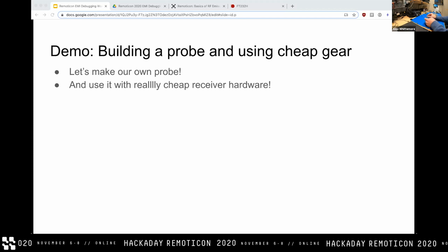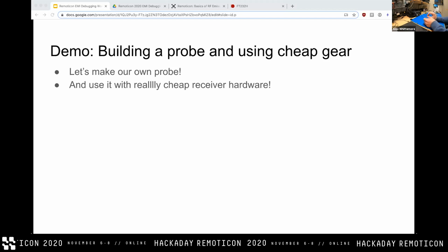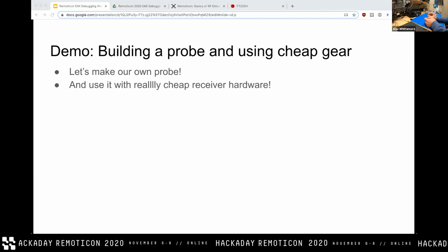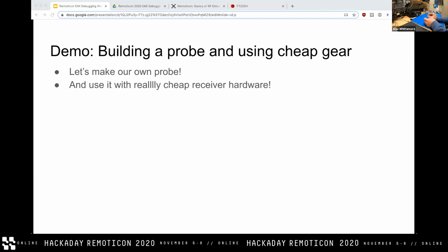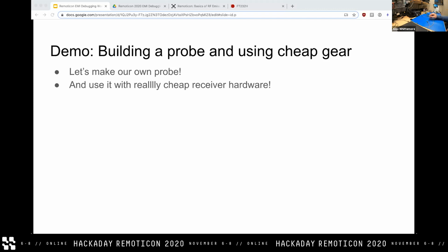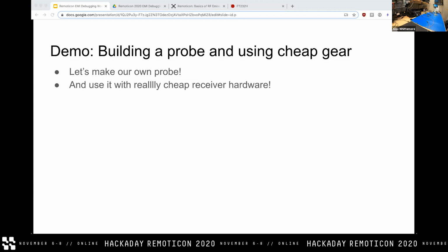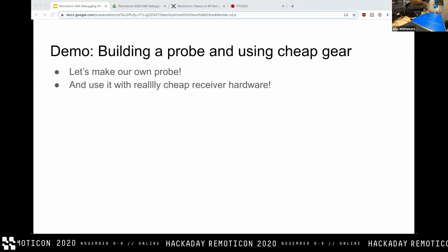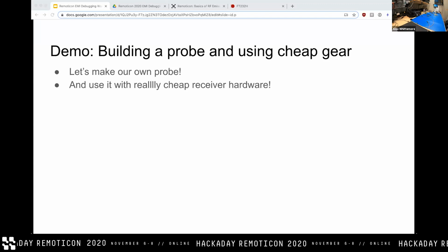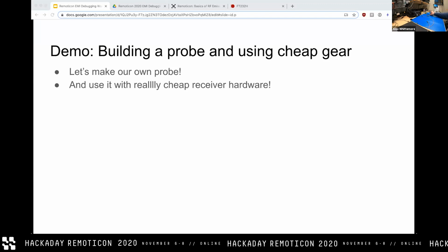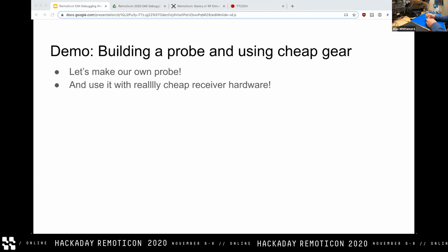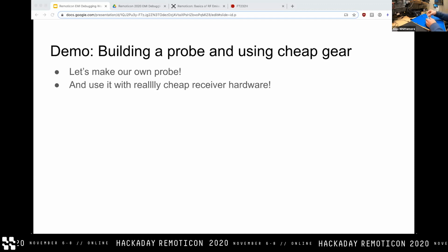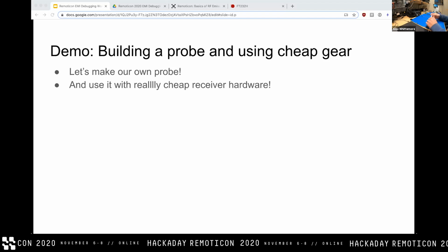So effectively, if you plug this antenna directly into the bias T enabled SDR and you have no way to turn the bias T off, you're just pulling tons of current out of the bias T. This SDR device can handle that for a brief period of time, but you basically overheat the linear regulator that powers that circuit, and after a few seconds or something like that, it will eventually burn out. So yeah, make sure you use the LNA between this device and your probe.